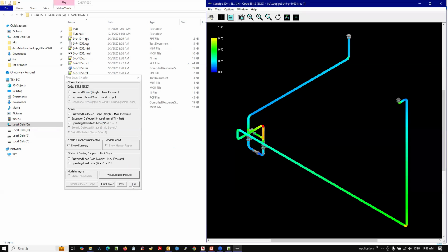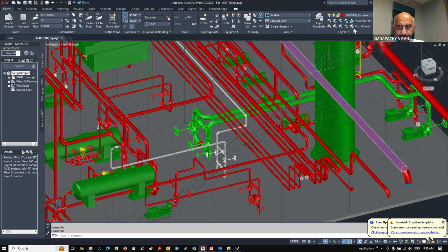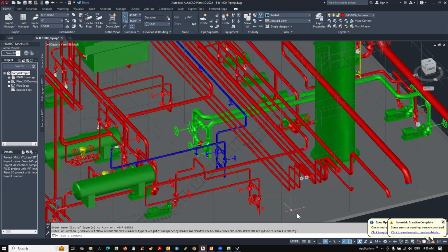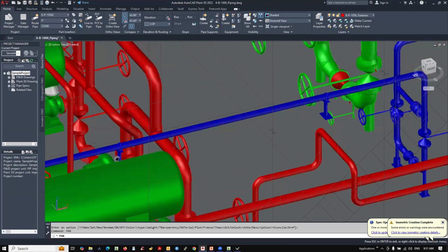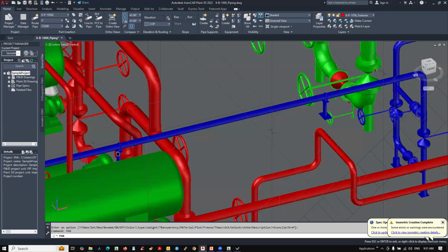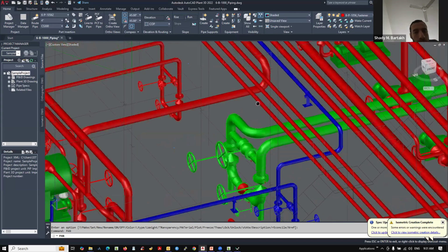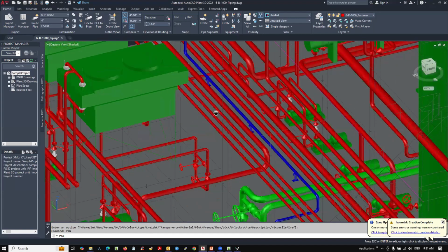Now what do you do? You go back to the 3D model and add a couple of supports here and also a couple of supports in this line. So let's say again he's going back to AutoCAD and assume again he has done the revised layer, and here is the layout. You see here he has added a couple more supports by looking at where the steel and concrete is. There's one support here, and he has added another support here. And then in this direction, he has added 3 supports. And let's say he knows where the steel is, where the concrete is.